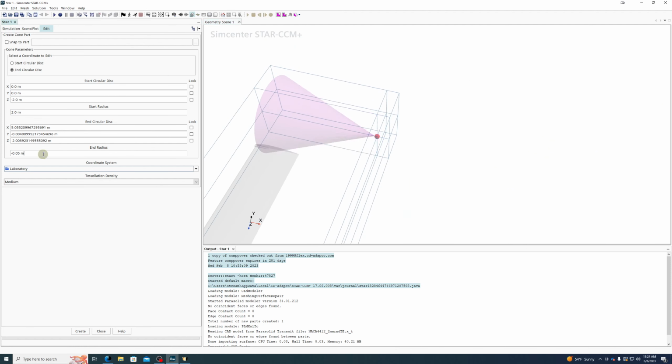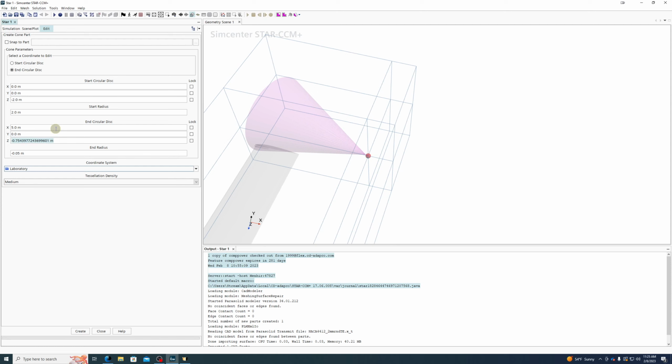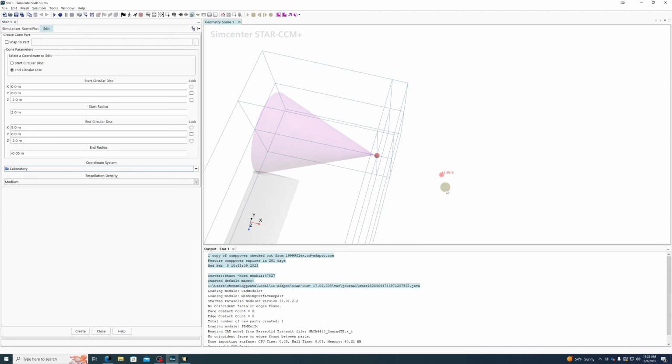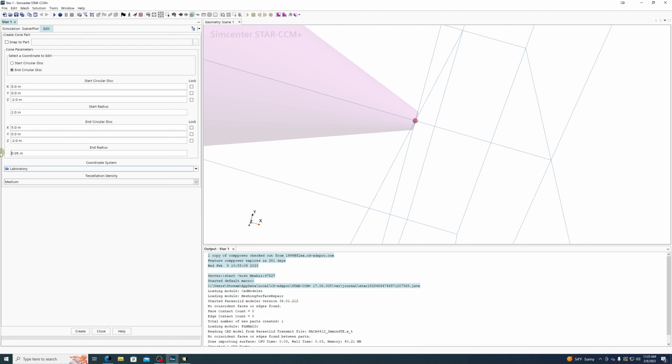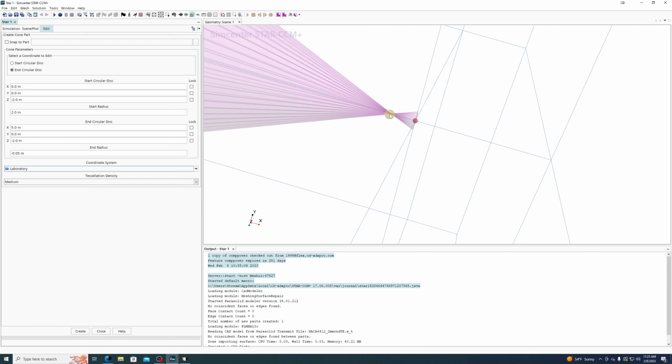And like before, you can drag this point around graphically if you so choose. It's a little bit less precise, obviously. I prefer to type in exact numbers in most applications because you get exactly the number you're after. That shouldn't be a negative value. Radius should not be negative. If we type in a negative value, that's going to do funny things like this. This is not good. Don't do that. Positive radius only.